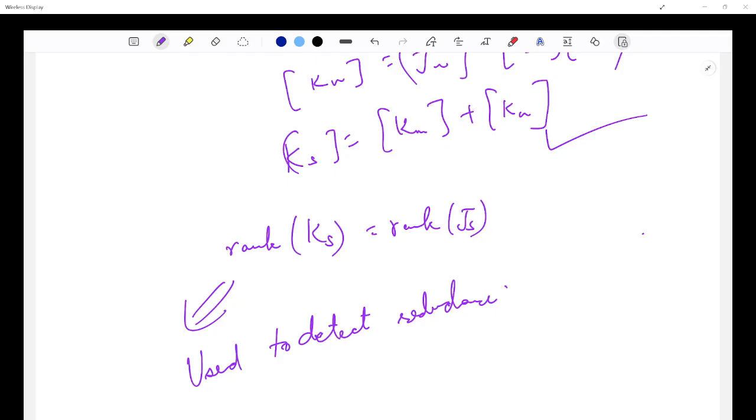Then we moved to over constrained systems, where the degree of freedom from the formula is not the same as the actual motion, but the mechanism still moves. So this is the most important idea today. And then the reason is special geometry, redundant constraints, and passive degrees of freedom that we already saw. Okay. And then for deployable structures, I think I should have mentioned.